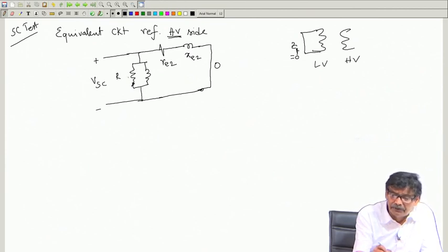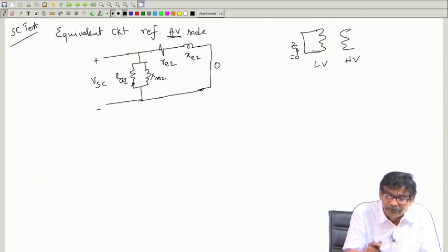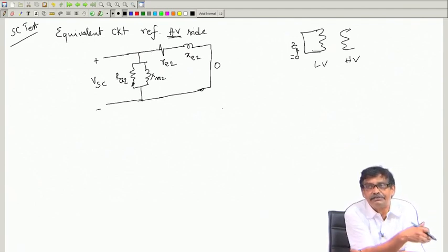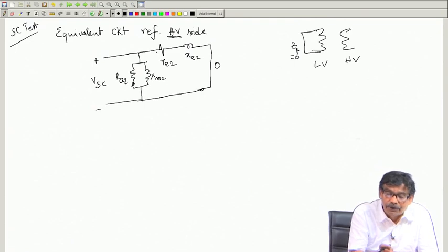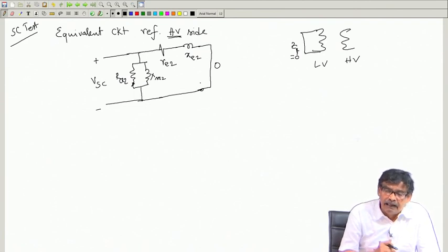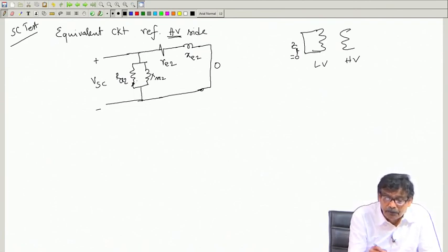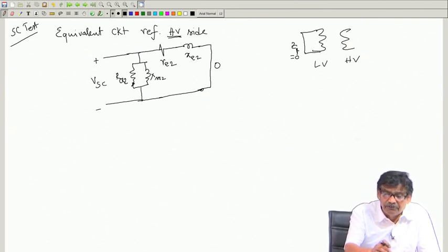And if I want to write this 2, I should write RCL2 and XM2. Okay. And RCL1 XM1 I have found out. Now, coming to the equivalent circuit and trying to establish the same thing. This RE2 and XE2 are quite small compared to RCL2 and XM2. These are high here, and also I am telling this core loss power can be neglected. Power in this resistance is your core loss during short circuit test, which is quite small, and that is also reflected in the equivalent circuit.